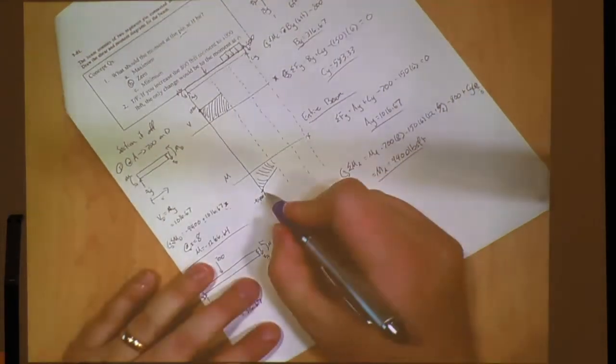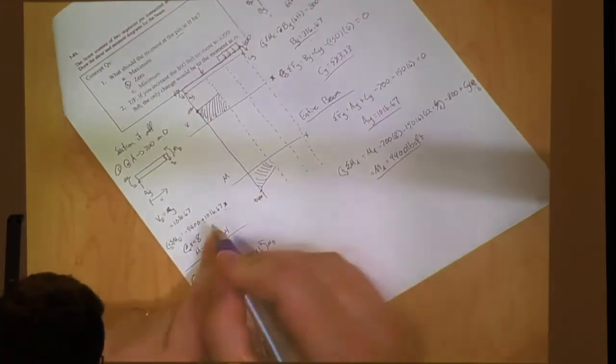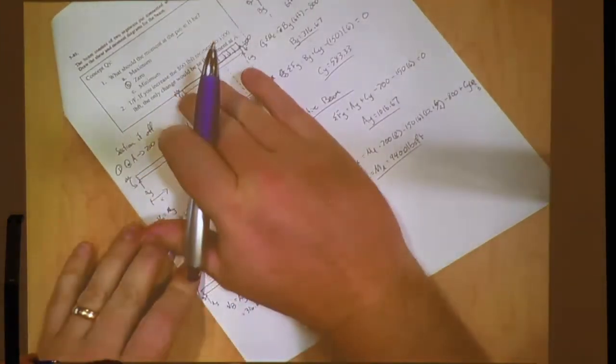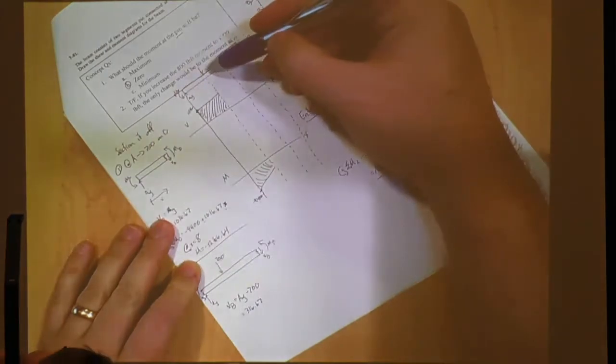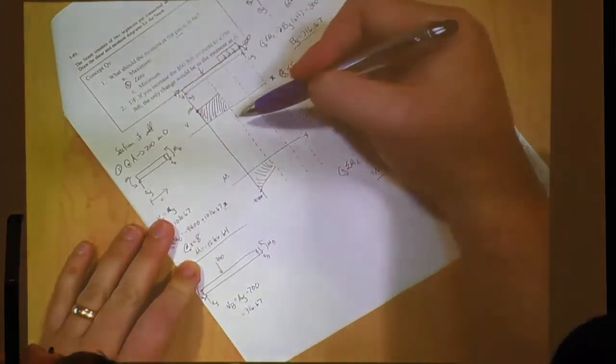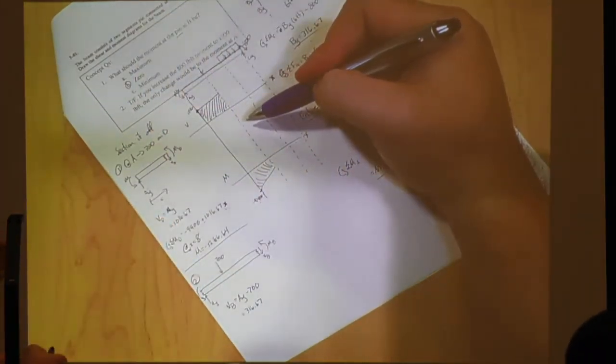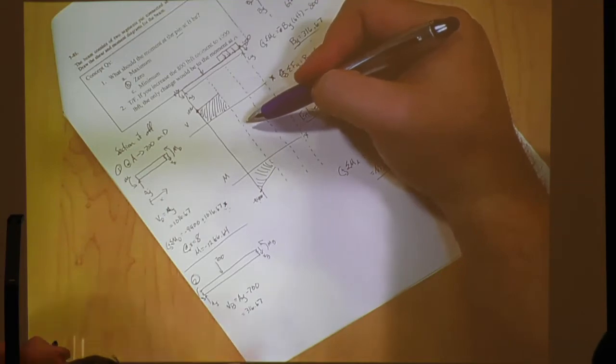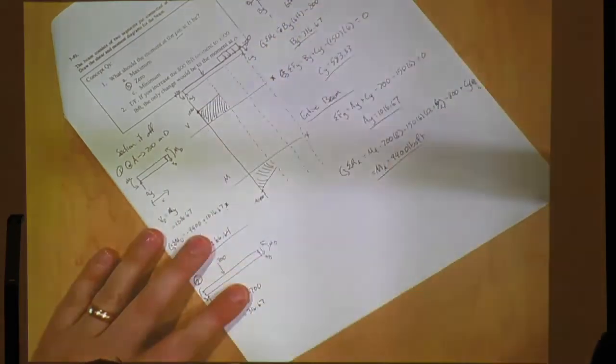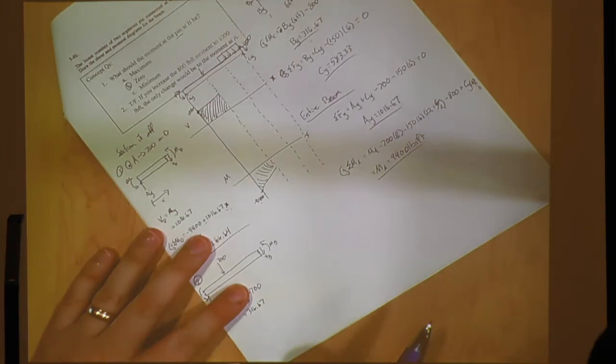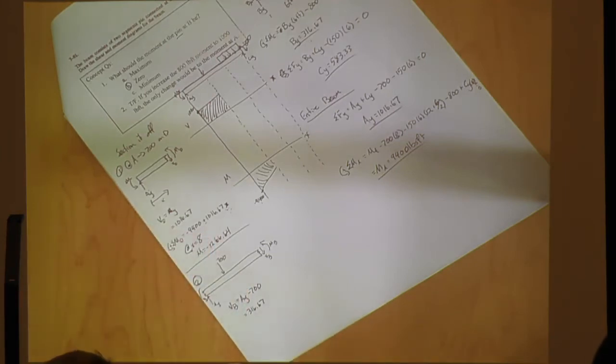This moment one? It doesn't cross the x because this is our equation for this section of the beam. The reason why we draw these lines is when the line intersects that point, the line equation changes. So each of these points is going to have a different equation for the line. You can't have a single equation for an entire beam.